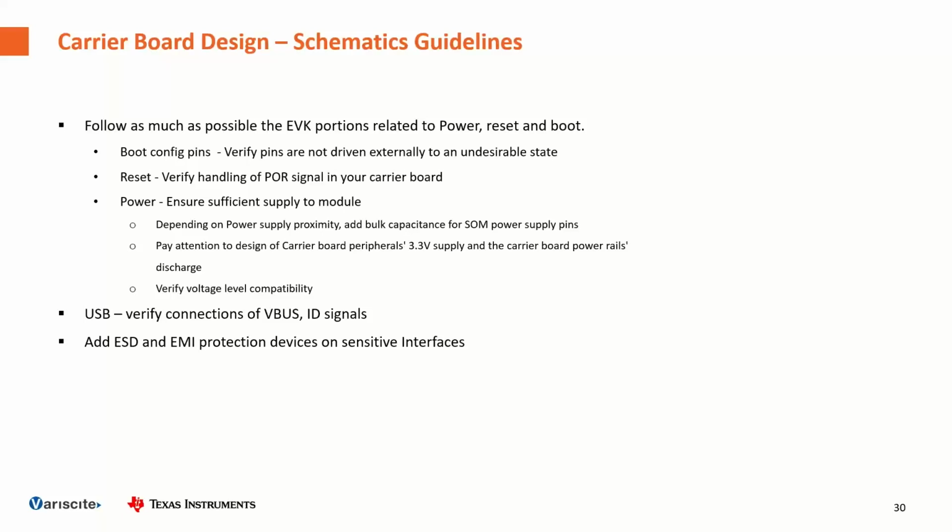You always need to ensure that enough power supply is provided. So depending on the power supply proximity, be careful with the bulk capacitance and pay attention to the 3.3 volt supply for the carrier rails. And always verify the voltage level compatibility.